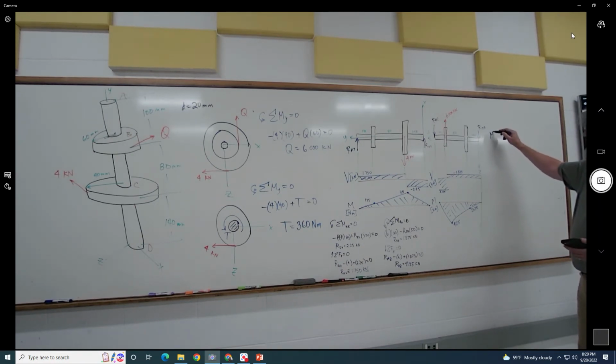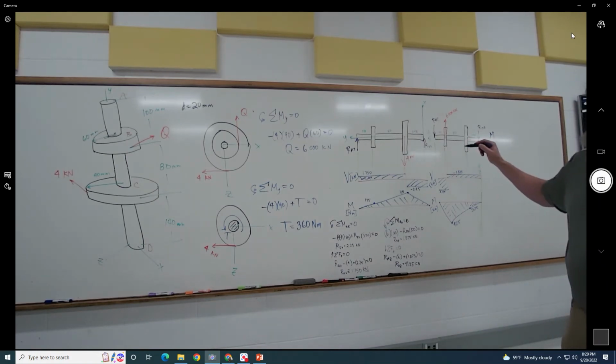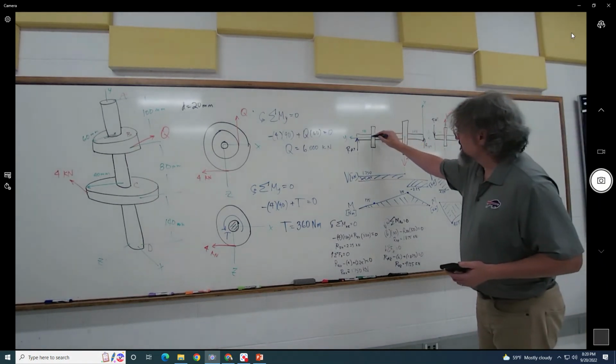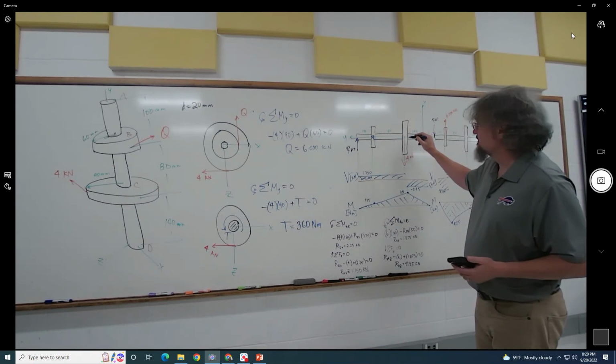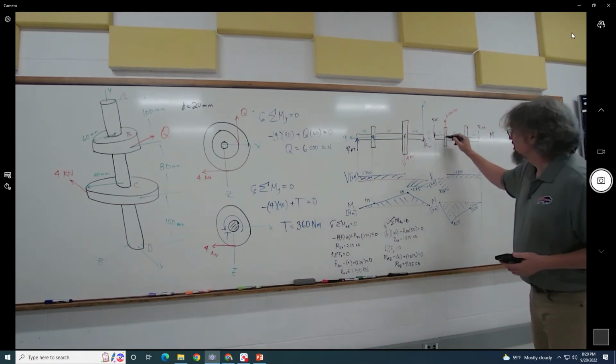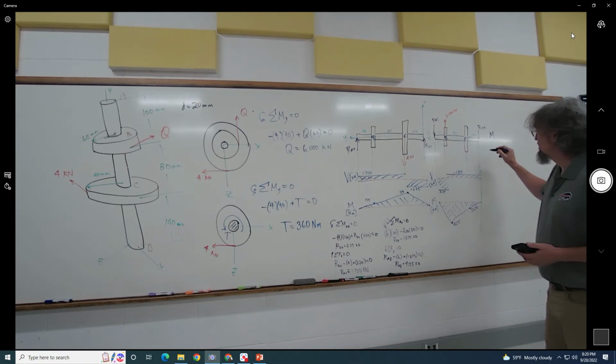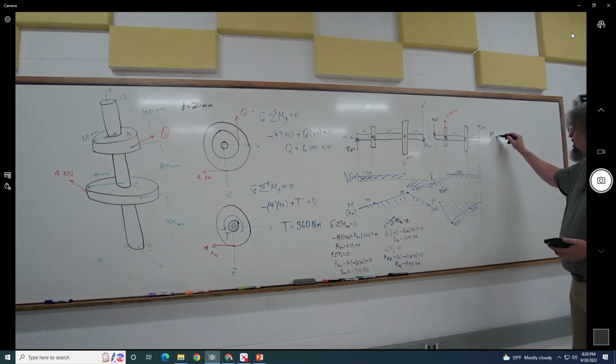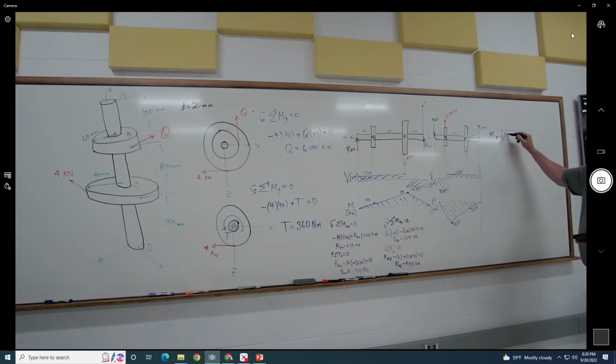So we have the moment that is taking place at B, because I forgot, this one is B, and this one is C right there, right? And that's B, and that's C. The moment at B, the combined moment is going to be 175 squared plus 412 squared.